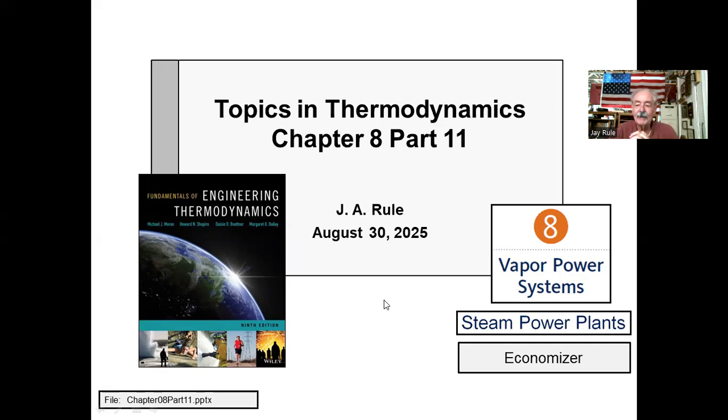And so you can probably see that the idea of waste heat is more of a measure of the furnace operation rather than the H2O circulating through the thermodynamic cycle. And so I have to be a little careful about talking about improving thermal efficiency of the cycle when we're trying to recover waste heat. So with those disclaimers, let's go ahead and see how an economizer works.